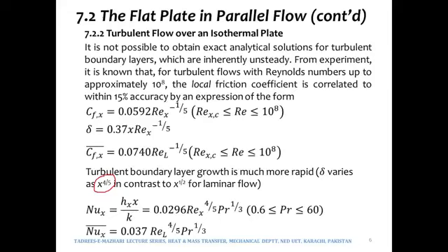So therefore the critical x, we may say that x critical is much less than L. x critical means the value of x where this transition from laminar to turbulent flow takes place. So in this case, if this is the condition 2 that we have been discussing, then x critical would take place at the start of the plate. So therefore x critical would be much less than L. So it may be any of the two cases.